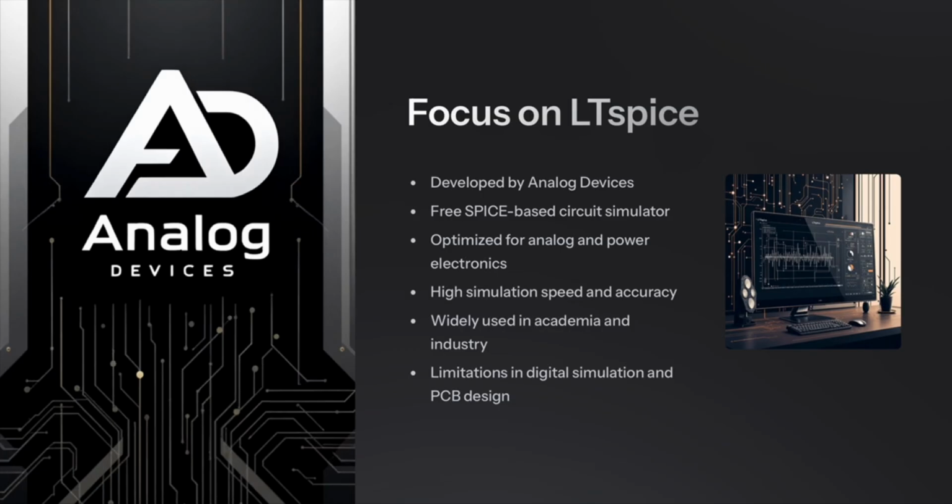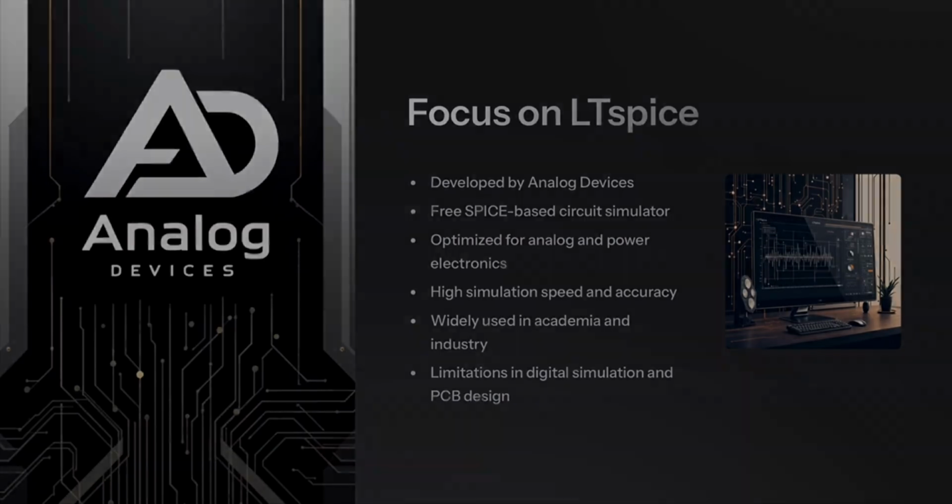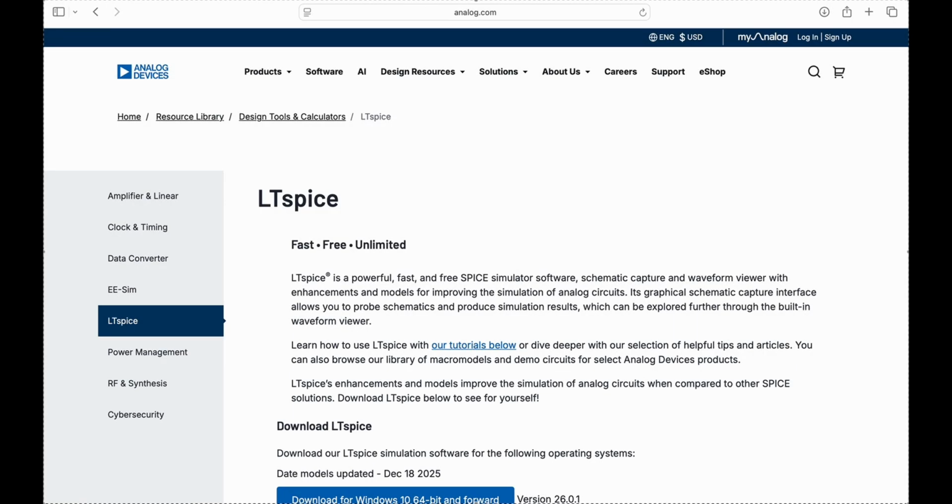However, LTSpice also has some limitations. It is not suitable for complex digital circuit simulation, and it does not support PCB design since it focuses only on schematic level simulation. Alright, so in this part of the project, I will show how to install LTSpice and how to use it for basic circuit simulation.